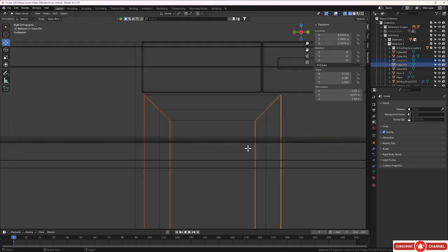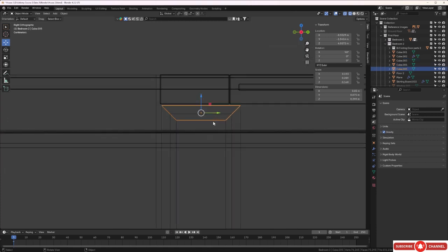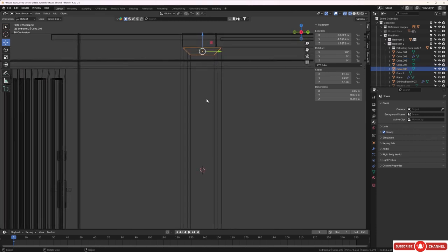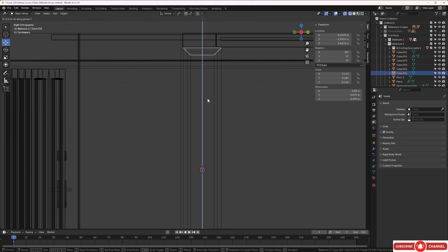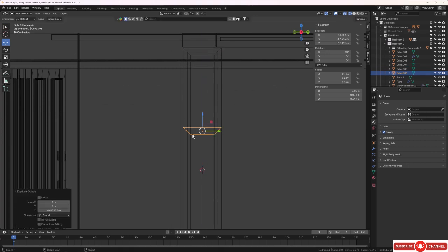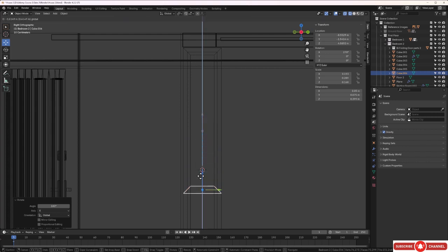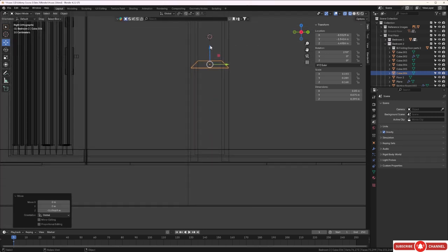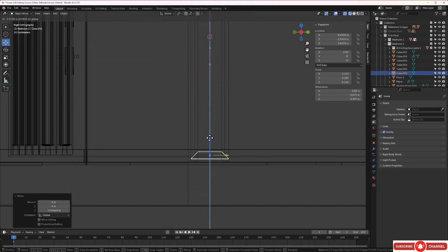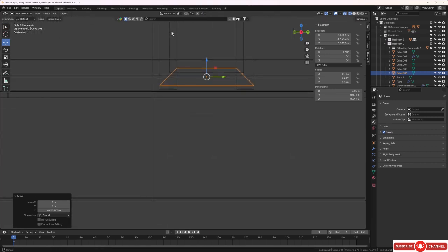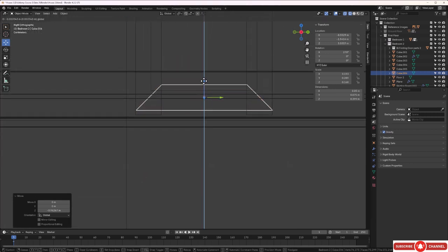Okay, let's tap out of edit mode with that and grab this one now. And let's press Shift D and Z and bring a copy down a little bit like this. And now let's rotate that, so let's press RX 180, enter, and now bring this one down to the bottom now until we are level with the two vertical pieces again.